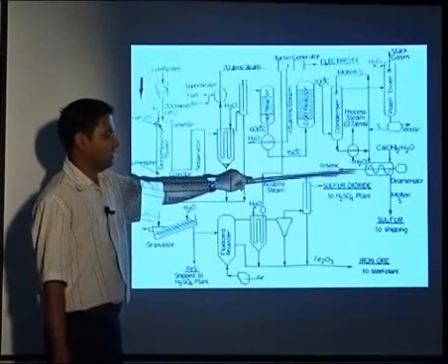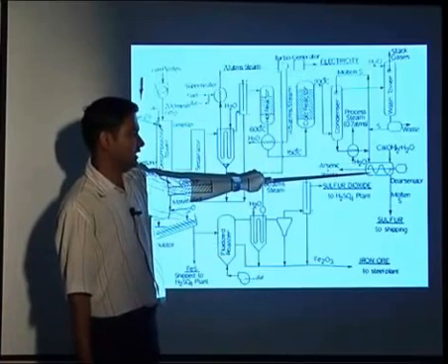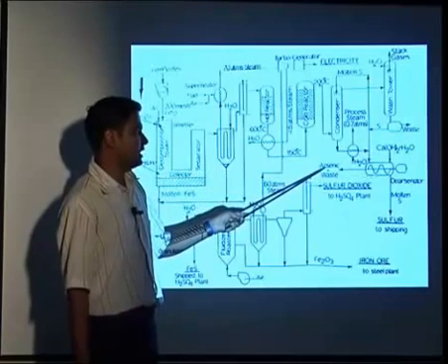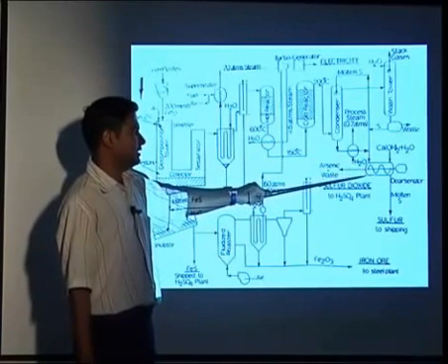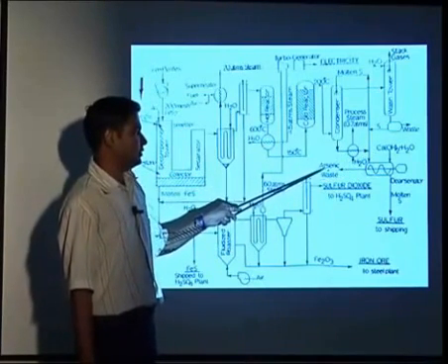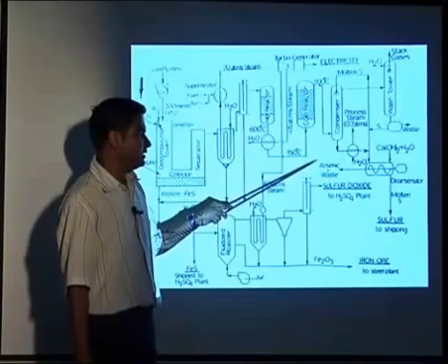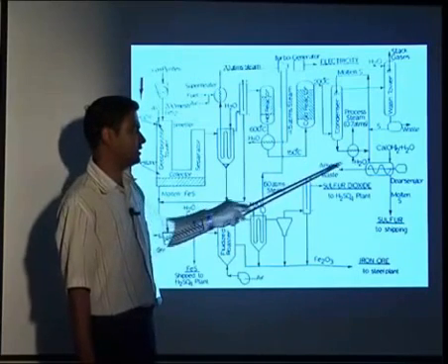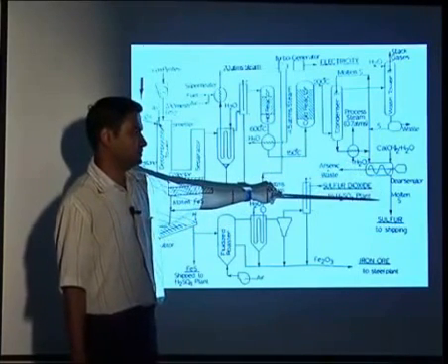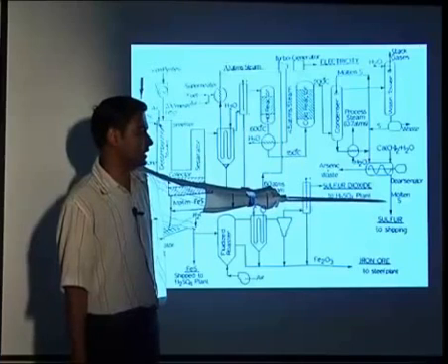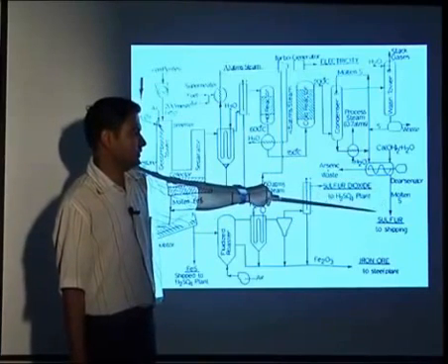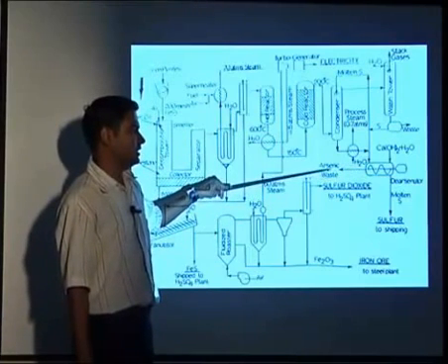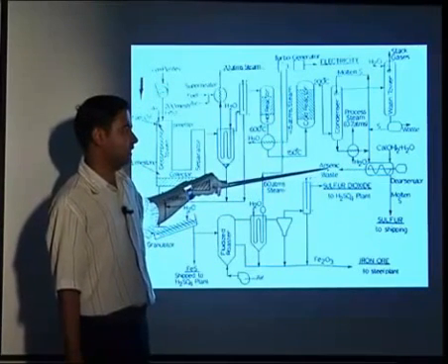So here the molten sulfur that we get, we are washing with calcium hydroxide to remove the arsenic and waste. It is necessary to remove the arsenic, because if arsenic is there, it will affect the vanadium pentoxide, which is the major catalyst in sulfuric acid production. The sulfur which we are recovering is generally used to form sulfur dioxide and sulfur trioxide, and then sulfuric acid. So the arsenic becomes the ill element here, and it will poison the vanadium pentoxide.